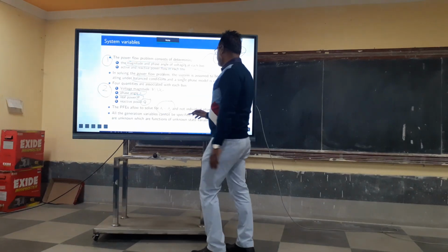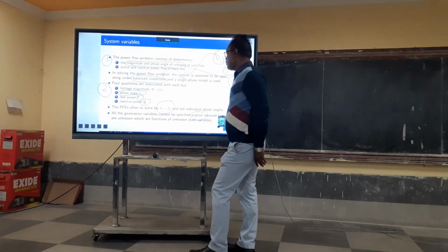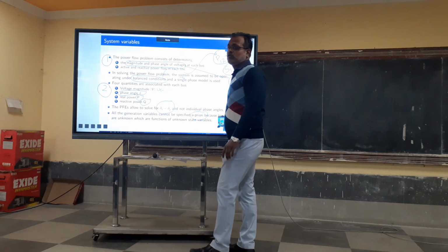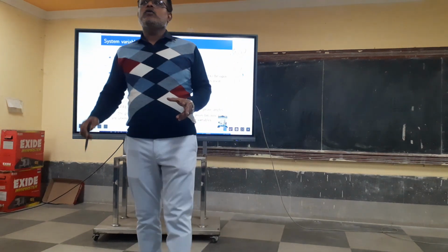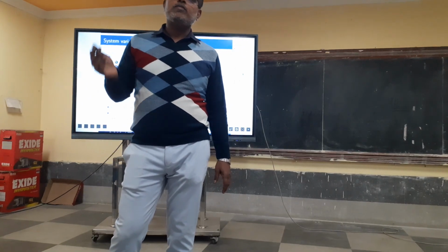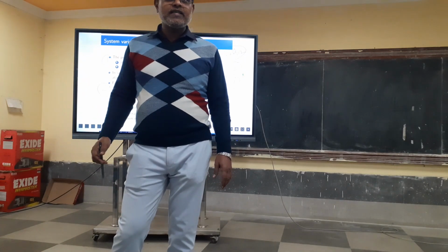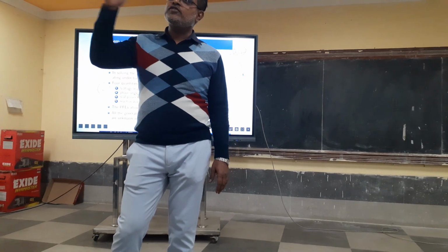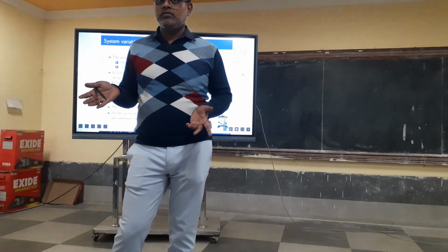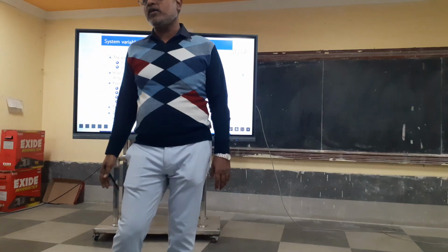All the generation variables cannot be specified a priori, that is, at the beginning before the computation, because losses are unknown. Say we need to transfer 200 megawatt of real power from the Hirakud power plant to some bus. We know that. But how much loss will occur in the transmission line, we do not know. Suppose while transmitting 200 megawatt you incur a loss of 2 megawatt.